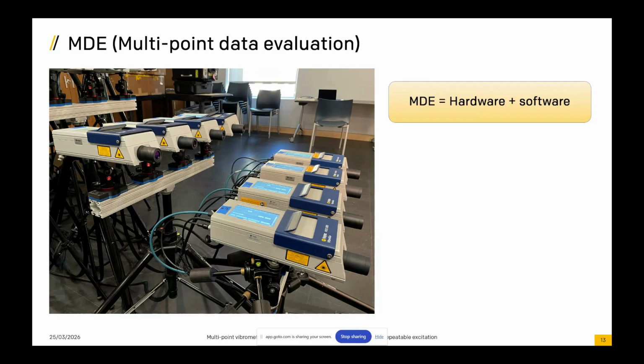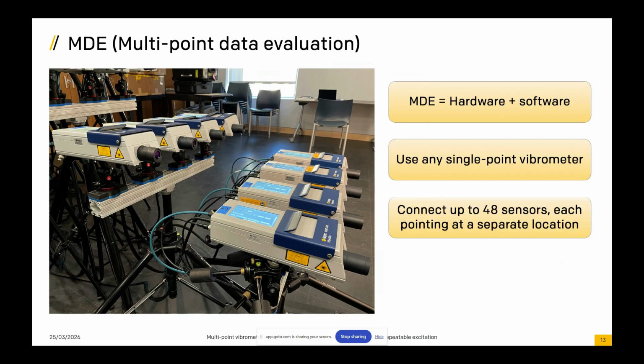So we developed some software to combine all of however many single point systems we want into one controller interface or data acquisition interface, or both. And the great thing is that we can use any single point vibrometer we want because it's agnostic to the type of Polytec LDV that we use.